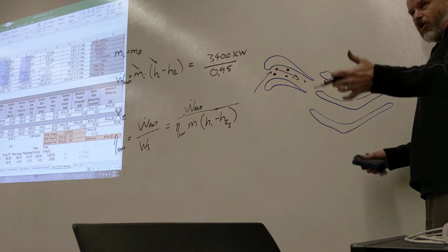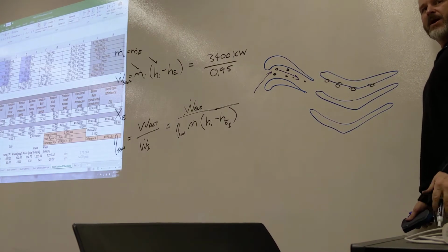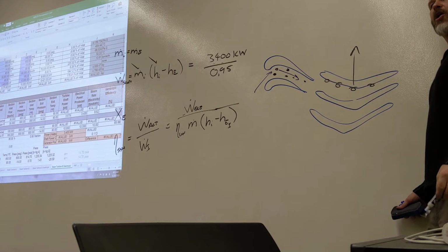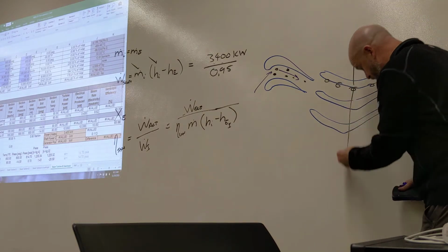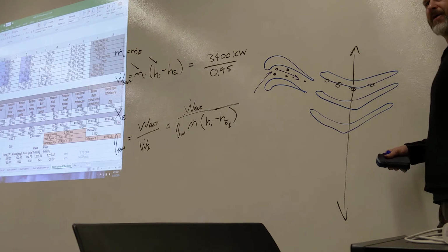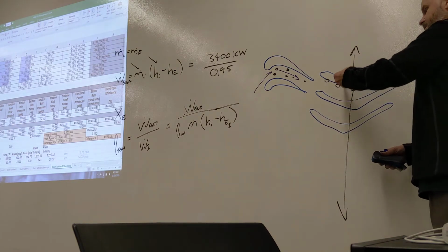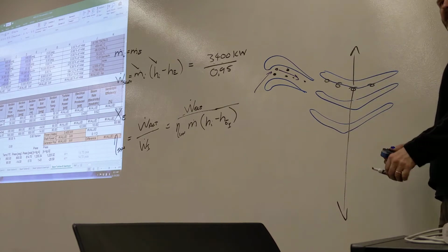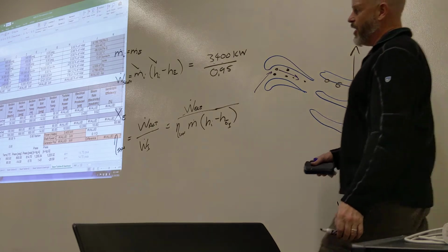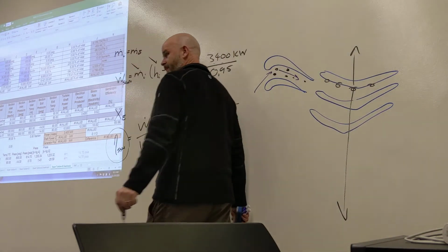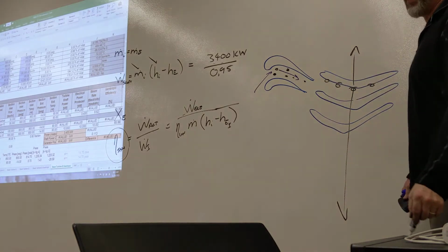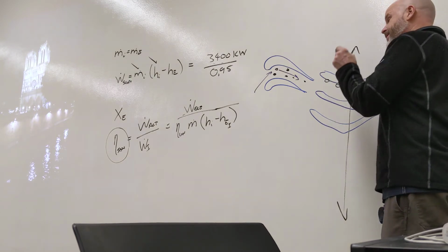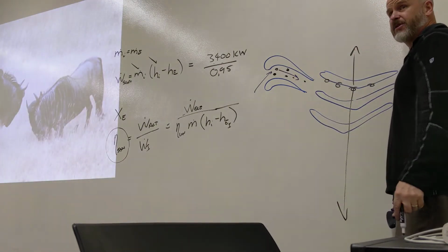Now this blade hits the droplets. Momentum exchange in the wrong direction hurts the efficiency of the turbine. We want a great big huge force going that way. These droplets are going to hit the wrong side of the blade. They're going to cause a force in the opposite direction. Not good for efficiency, a bad thing for efficiency.